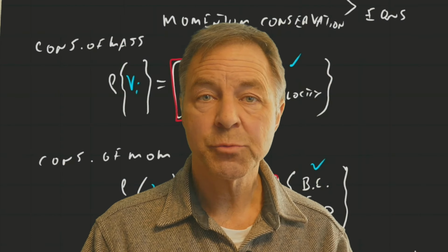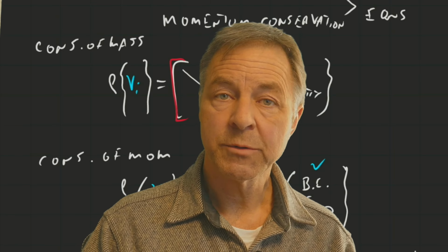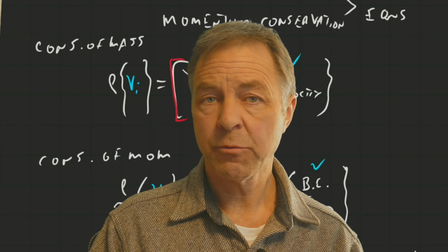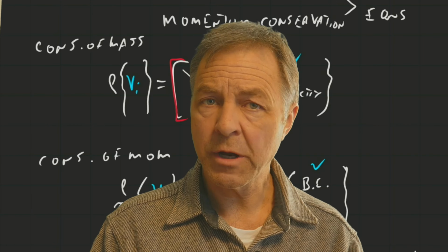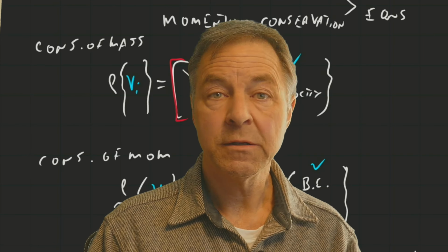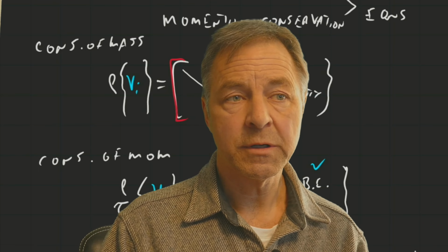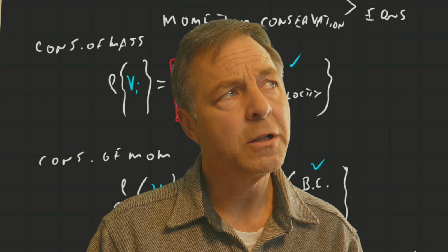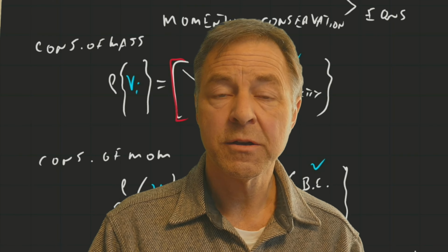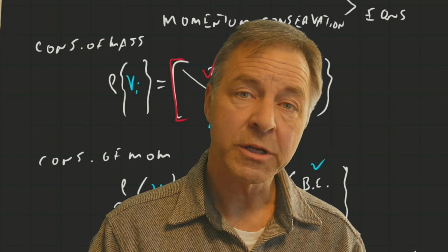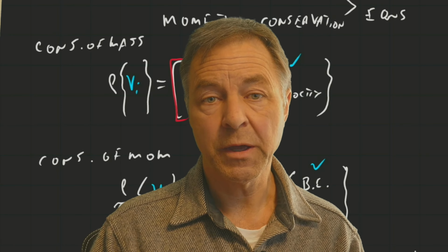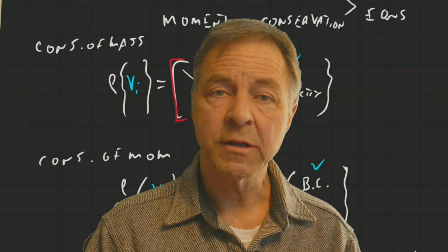There, so our first run of this model, we've got a result. The result was 14.5 newtons of lift and 3.9 newtons of drag. The lift over drag, therefore, is going to be something like 3.7. That's a lot less than the 30 to 40 that we're expecting from looking at the drag curves and lift curves for this particular airfoil.